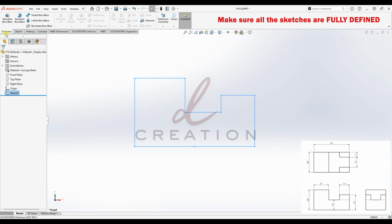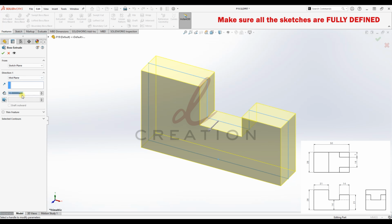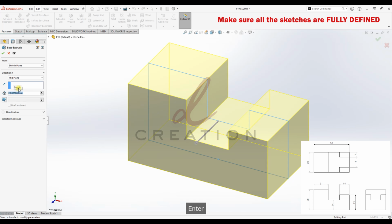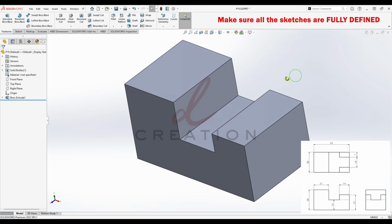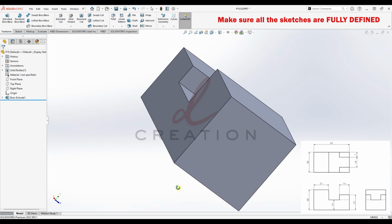Exit sketch, go to features, extrude boss base. Now we can extrude using mid plane, and the thickness is 28 mm. Okay, and then click OK. So I turn off the real graphic feature. Now you can see that we have the solid model, and we are going to cut over here.